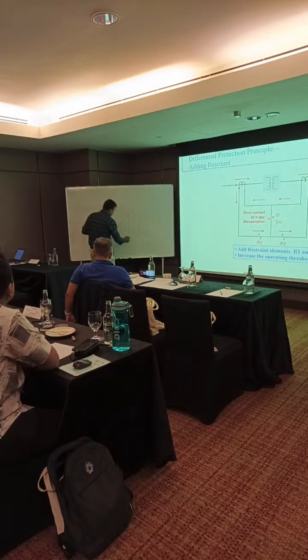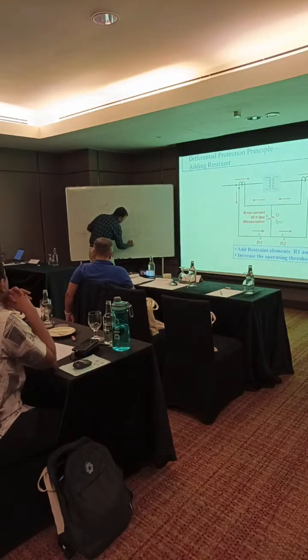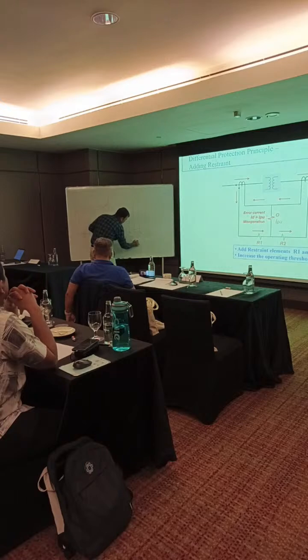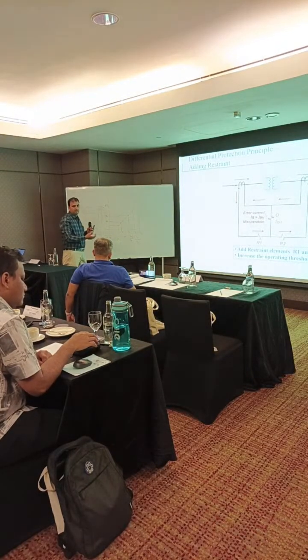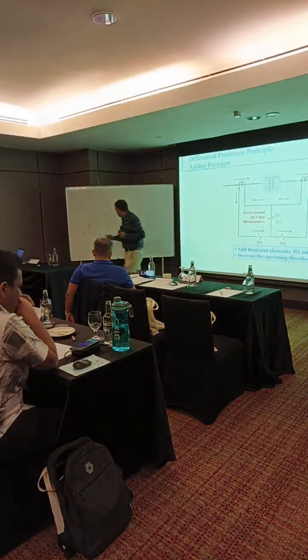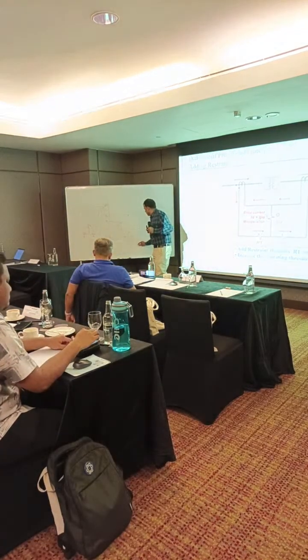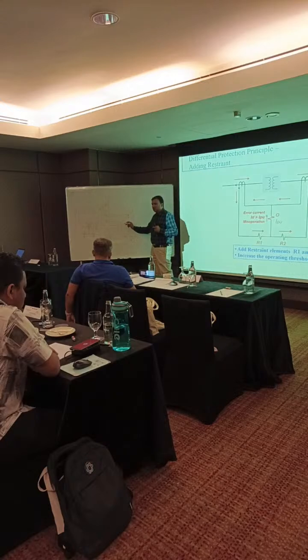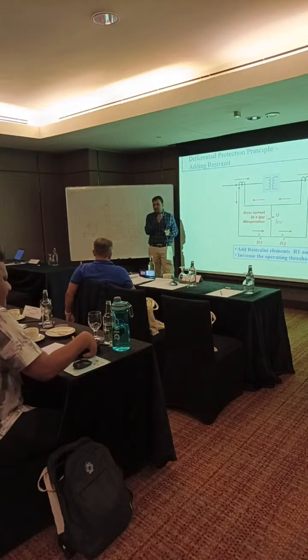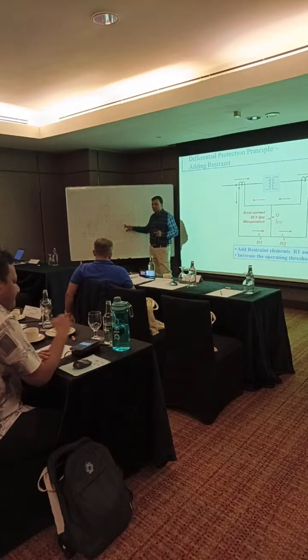If you want to calculate that, then ID2 minus ID1 divided by IR2 minus IR1 is equal to M. Slope K or M, whatever you can say. This is how you calculated the settings yesterday. The same way you can inject, and these values you can read in the relay and calculate the slope.